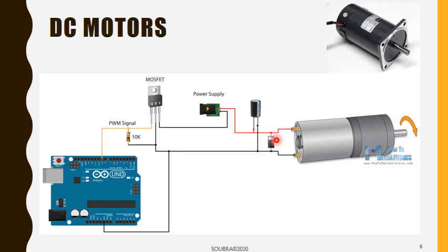The last element that you're seeing here is called a diode, and you can see that it's polarized: this is the positive side and this is the negative one. It's connected in a parallel, opposite way to the DC motor in order to secure the system and do away with the potential kickback of the motor.